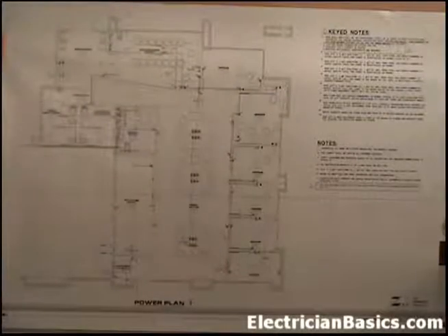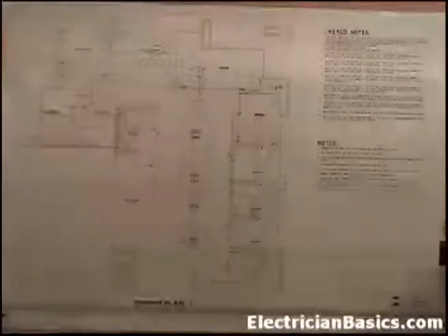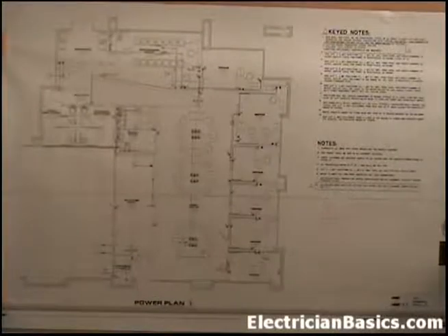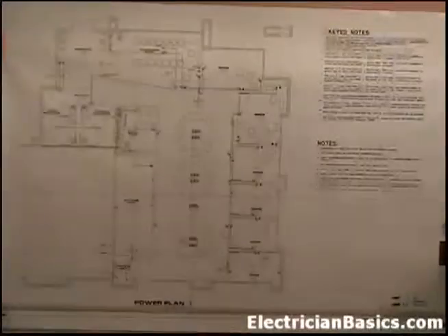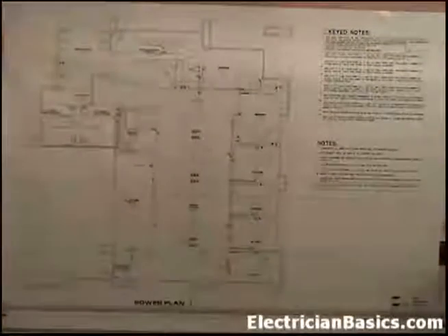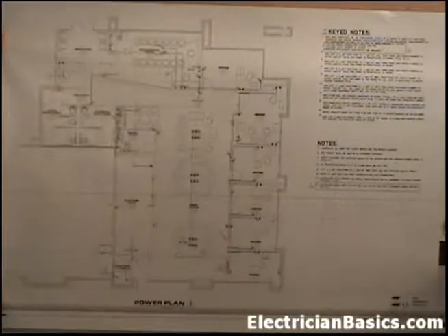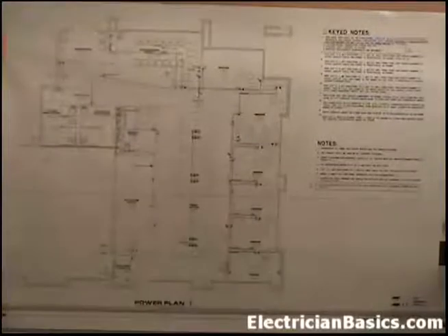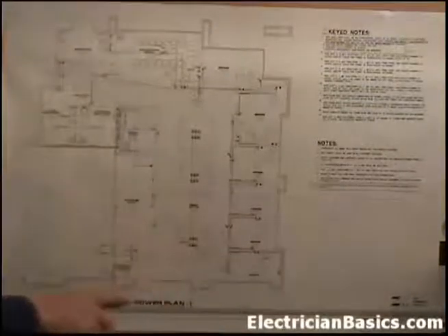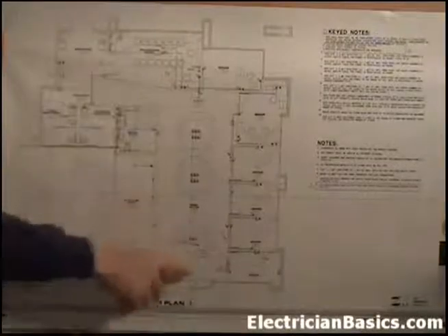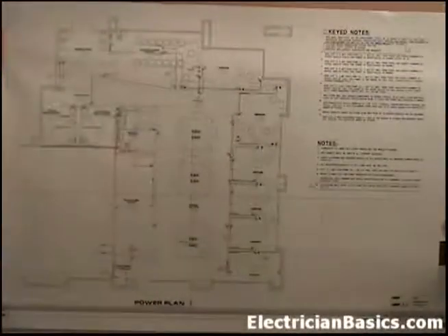You can follow along on sheet E4.1. I've made another copy of this and started some red line drawings on this sheet, and I'm going to show you some things I've done on how this was built out and how you should do red line drawings. Let's look at this area and some things that I put in with the red line drawings.